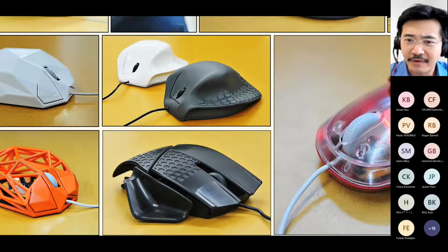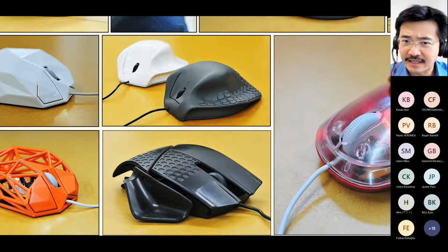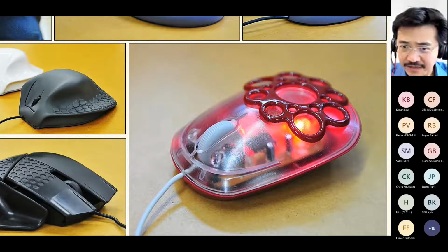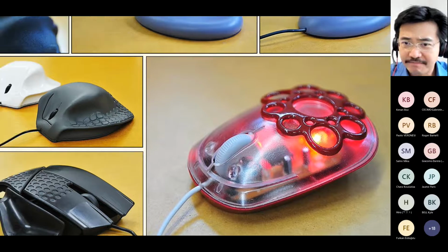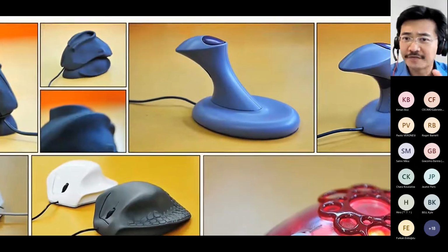It wasn't very easy at that point of time. You could have an extrusion or an emboss feature, the parting lines, bringing them together. You need to get the right fit and tolerances, or even to get transparent or translucent materials. At that time, 2011, 2012, it was not that easy, and to also get the mounting bosses, the snap fits, and that detail, and all of these computer mouse or mice would have to work.